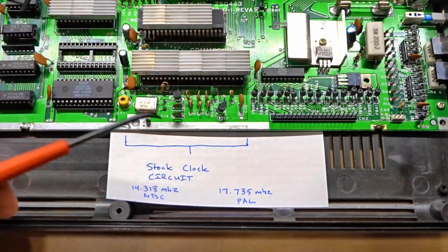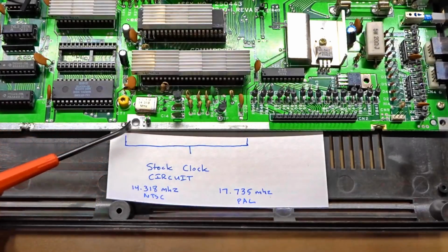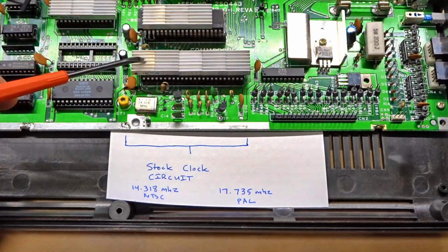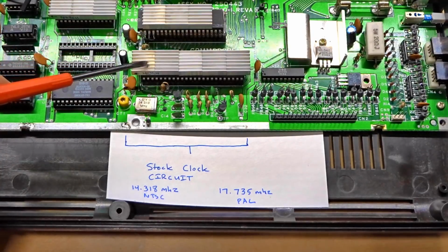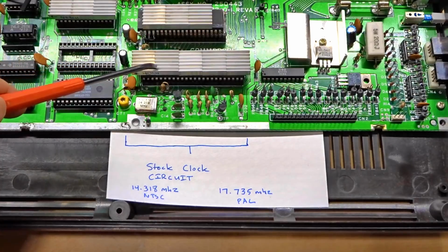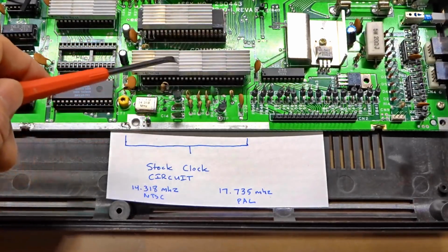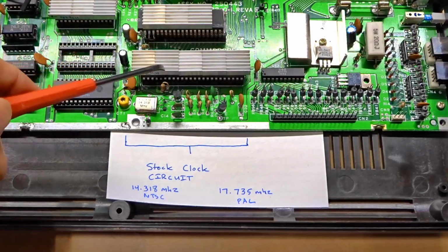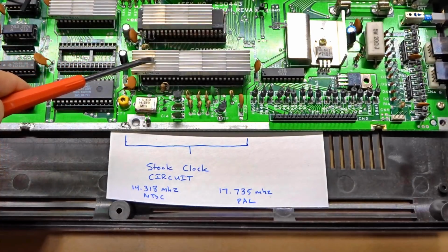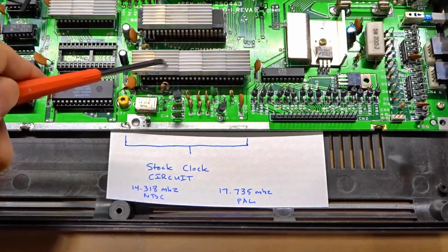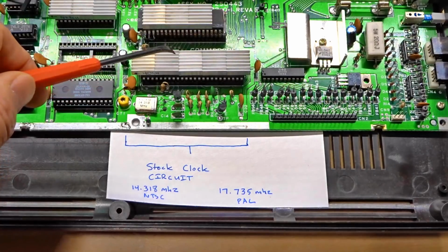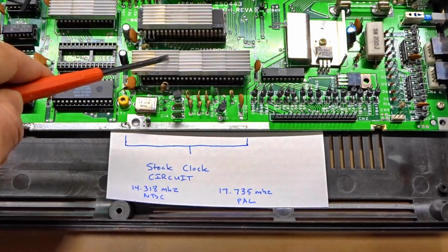So down in this section, we have the stock clock generator circuit. This is the TED chip, which is the brains of the Commodore 264 style of machines, generates the audio, video, and all the clock signals. It's very programmable, and with the clock signal that's sent into it, the kernel is what determines if this is going to be an NTSC or PAL machine. So unlike on the Commodore 64, where you need to have a different VIC chip depending on PAL or NTSC, this one chip is completely programmable for what type of output you want.